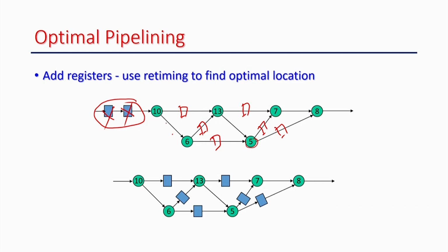Initially the circuit has a maximum delay of 5, now the maximum delay is 2. So, from 5 I move it to 2. Pipelining in the sense that we place extra registers at the input, and then we utilize the retiming tool to move the registers in the circuit to improve the pipelining.